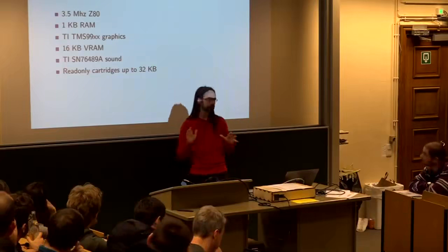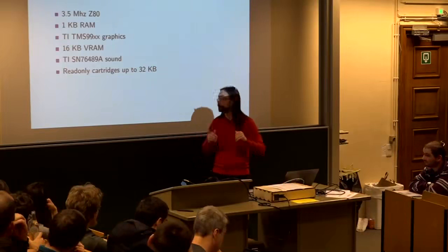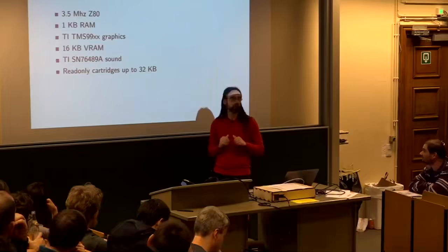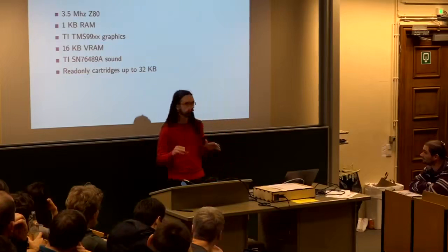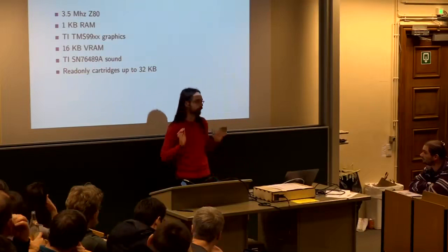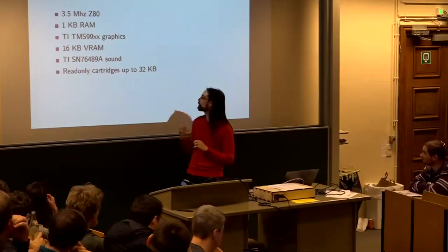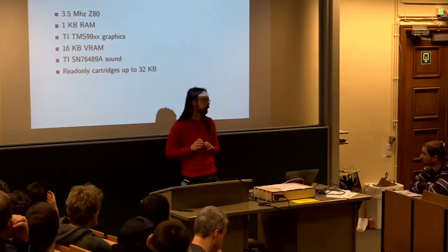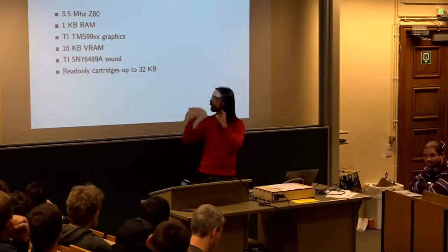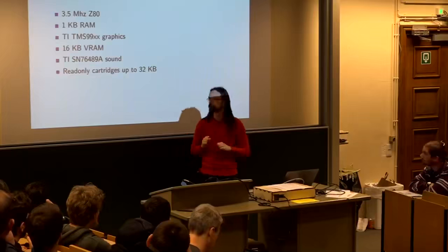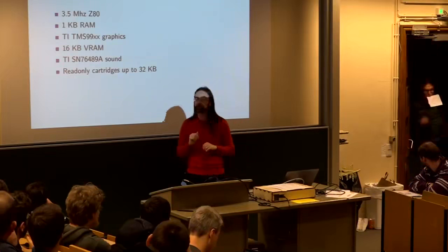It has a cartridge port that's kind of designed for EEPROM or PROM cartridges with up to 32 kilobytes. It's clear that it was only meant to read from those cartridges. They don't even expose a write enable line on the cartridge port. That makes it hard to design something bigger for this port, because instead of just using the write enable signal and saying, okay, I'll map this I/O into the memory space, you'll have to interpret read signals coming from the system if you want to do something fancy on the cartridge port.